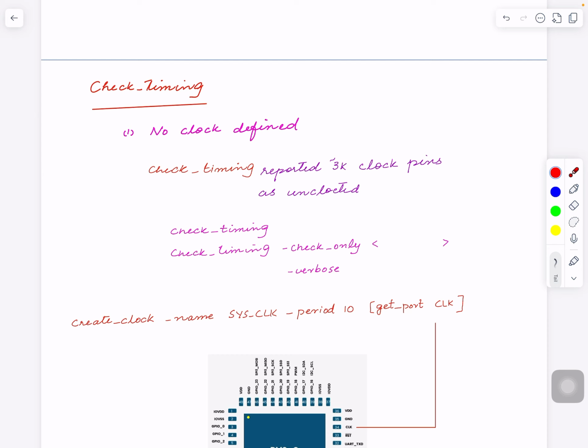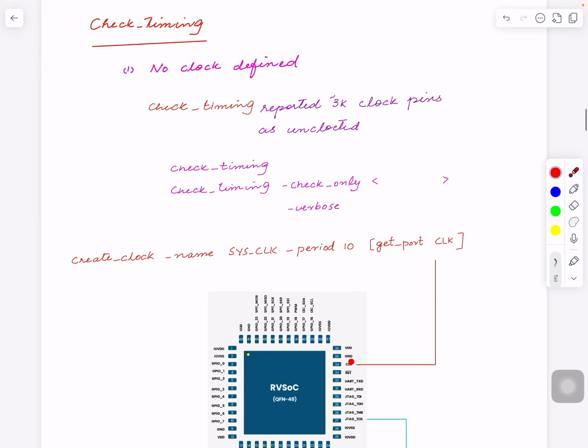Some of those we analyzed with the all fan in command. Yeah, we use all fan in and all fan out a lot to go back. So without knowing any specs from any RTL description, we figured out where the clock was missing. We did all fan in, and on different flops, when we did all fan in to the clock pin, it came back to this pad. Okay, so we created a clock definition on the pad.